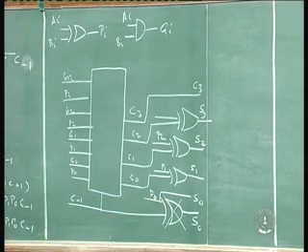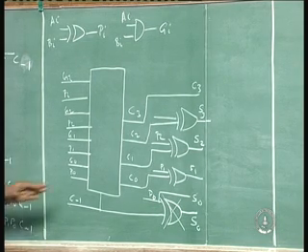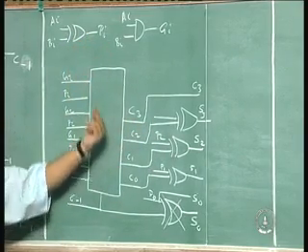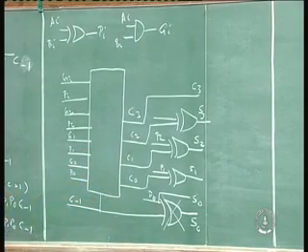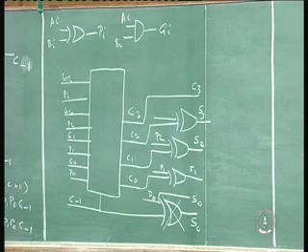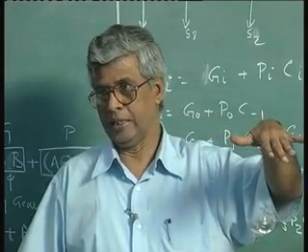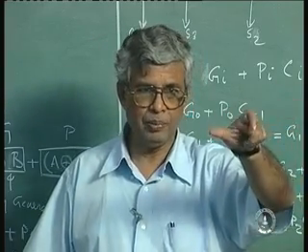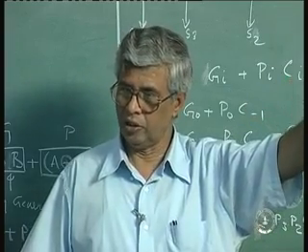So now I have one more stage, and now the carry is generated. One gate to transmit, one gate to compute sum, one gate to compute these P's and G's, and 2 levels of gates to compute carry. Now this does not depend on the number of inputs, so the propagation is always the same. In a multi-bit adder, each of these carries will be generated after 2 stages and fed into the next stage. Every bit addition requires 2 stages of computation, and then the last carry, C3, will come.